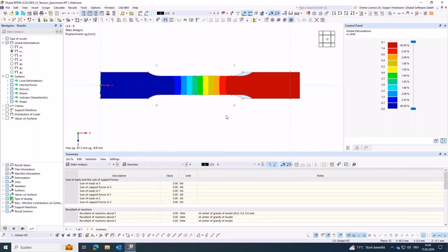There are some other topics where you will need the initial state. So one thing are geotechnical analysis, where you have a load history of the materials used in the soil. And the other ones are the form finding add-on, where you need a load case of pre-stress to get a stable model, or maybe tensile membrane structures or some rope structures. Yeah, okay, that's for the initial state.